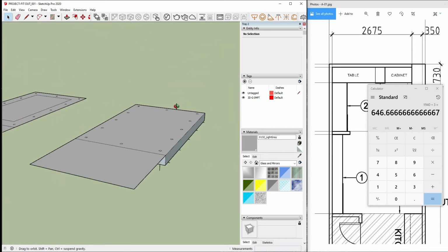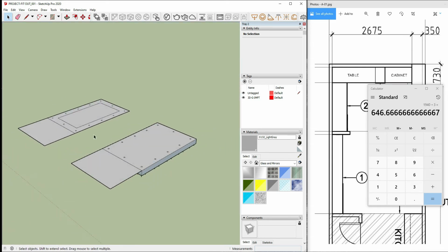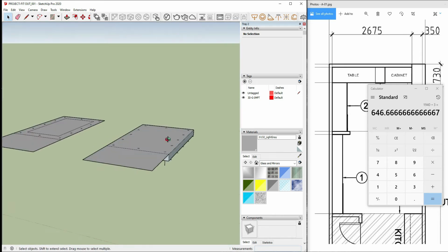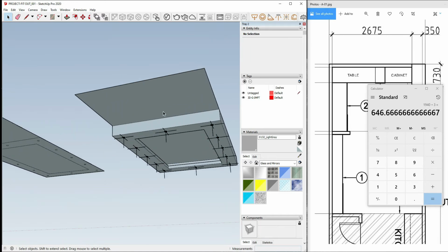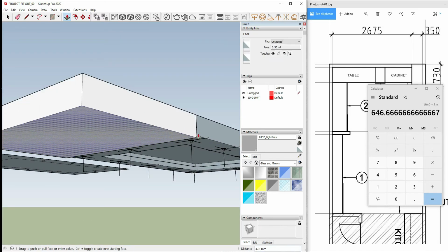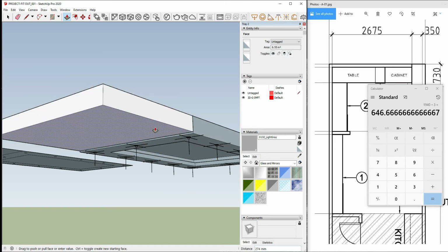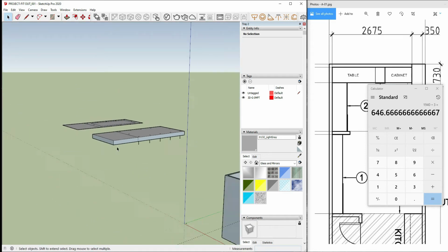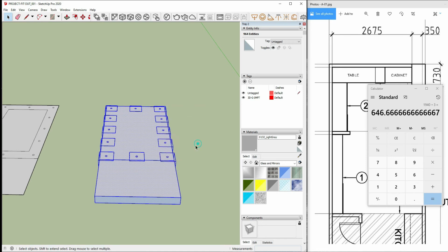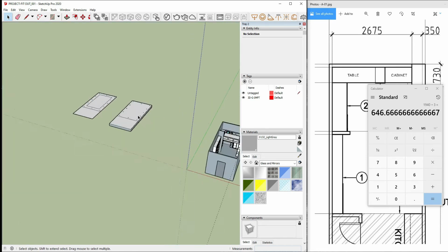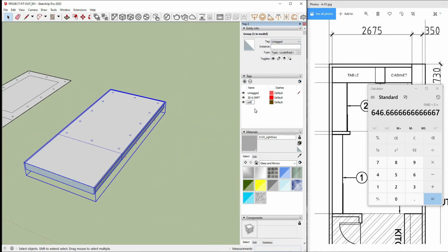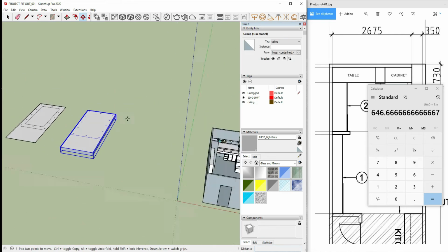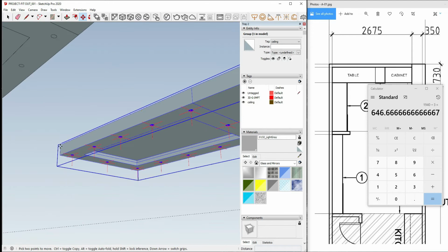I create a copy of this object and place it in each circle, which we used as a reference point. Easily, we created multiple copies of the lighting fixture with V-Ray lights on it. After we make multiple copies of the lighting, I make the object a group and add it to the layer to easily isolate it when we are modifying our project model.